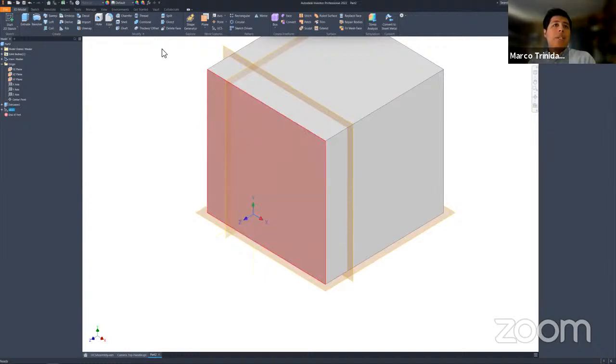But when you place it, you do need a point. So you can select a point on your part, and then it's going to prompt you to select the x-axis first. And you do have to pick another point. So you can't do it on this line or anywhere that isn't a point. You're going to have to add in a point if there isn't one by default. And then it's going to prompt you for your y-axis. And that's how it's going to place it.